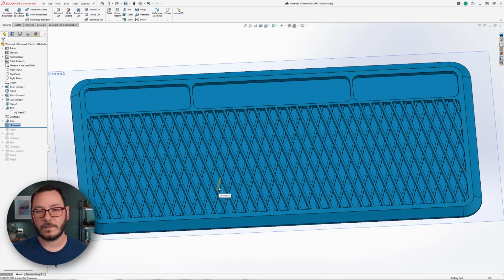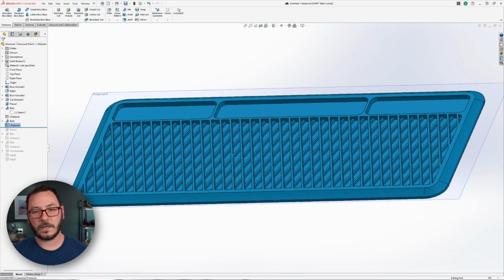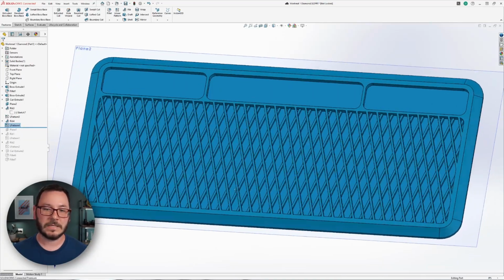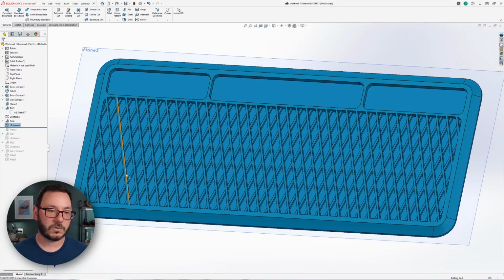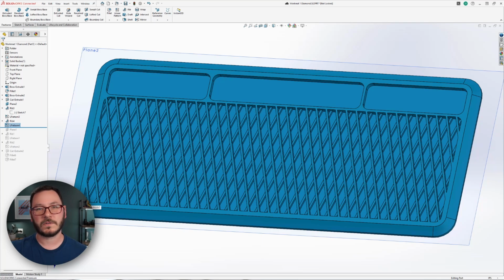And again, this is a pretty bulletproof method. Oftentimes I will use this myself as well, of just bumping up a little bit and then cutting them back to where I need to go, just to get the advantage of using those end conditions. And again, this is a benefit because as you look towards the corner, you're seeing all of these geometry actually being different pieces. So we would have to go in and draw all of those individual shapes if we wanted to do this manually, where the rib takes care of that for us.